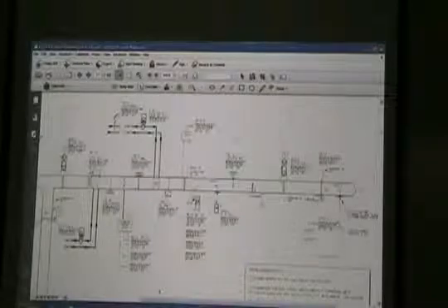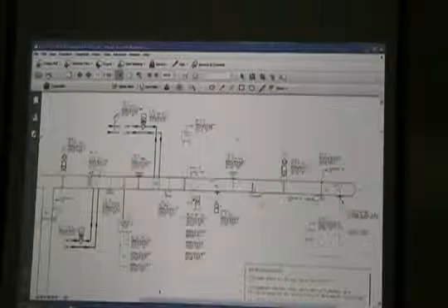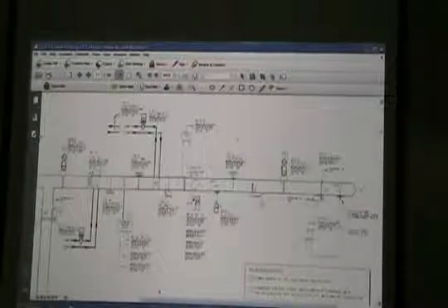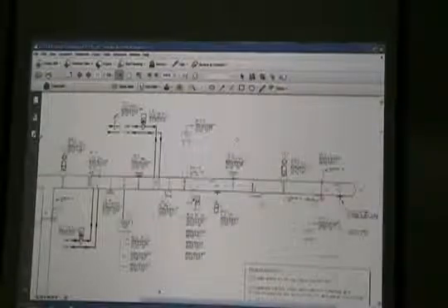So when that switch makes that low temperature set at 40 degrees, it goes through the process of stopping the fan. But we're also monitoring right here with a point. Through that point we can go through software. We can probably still pick it up from the drive, but from that point we'll monitor it. And if we see the switch make at 40 degrees, then we can go through the process of programming to open that valve 100%. The reason for that is you get full flow through that coil, less likely to freeze the coil.